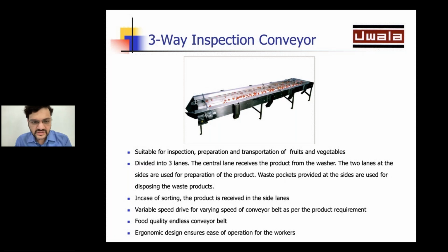Again, all the machines that we will be showing over here are made completely in stainless steel, because mild steel is prohibited to be used in plants like these, because if they tend to rust it is almost like poison. So it is not advisable to use mild steel at all in any of the machines. All the machines should be made completely from stainless steel, or at least we should ensure that all the contact parts of the machines are made completely in stainless steel.